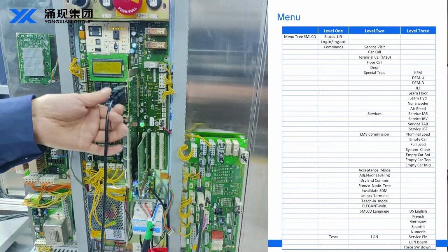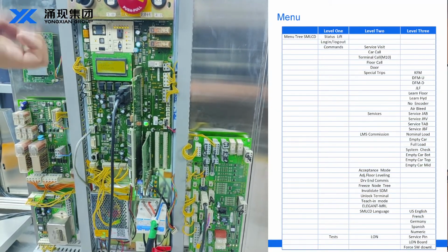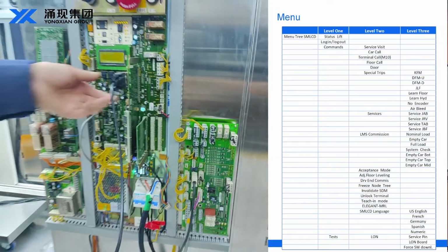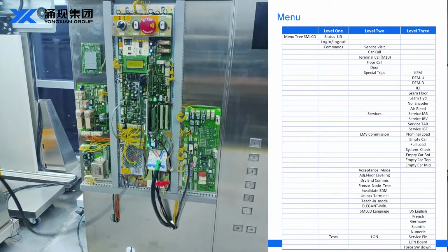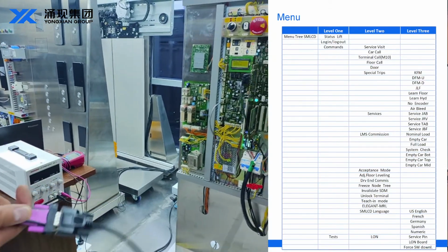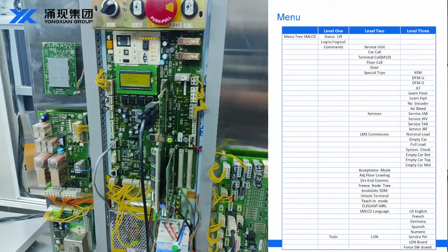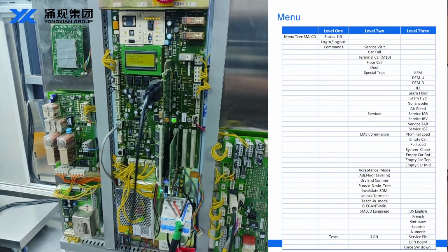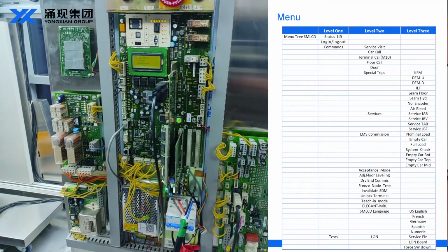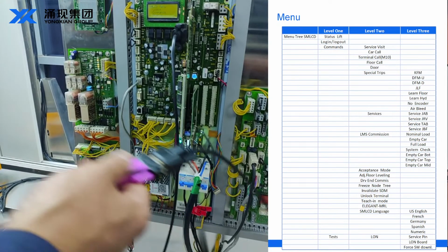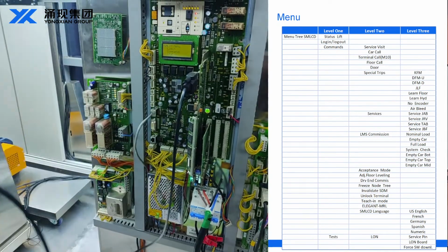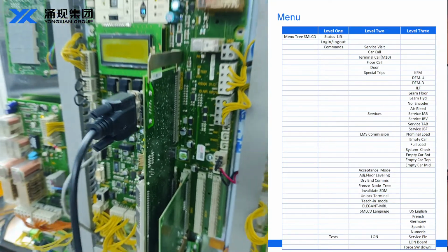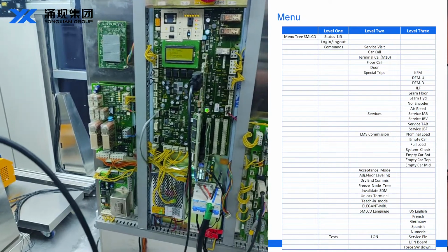Next, we talk about how to repair and commission elevators and solve problems quickly, starting with Schindler's dedicated software CADI. Many people care about this software, so we will tell you directly. First, the connection cable of the CADI, from RS232 to USB.